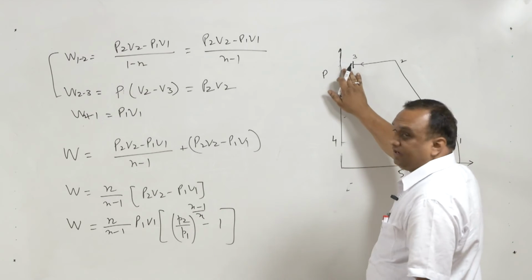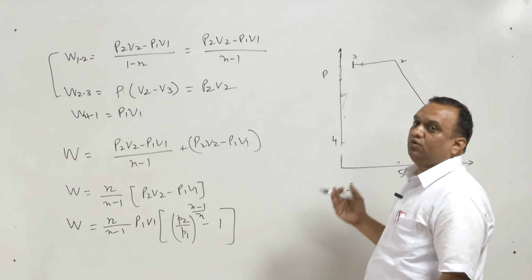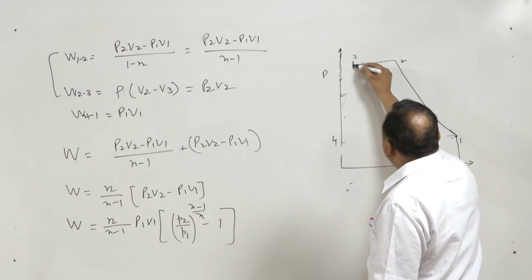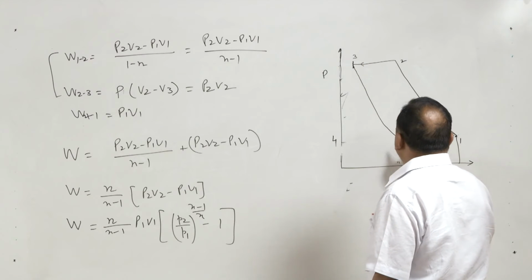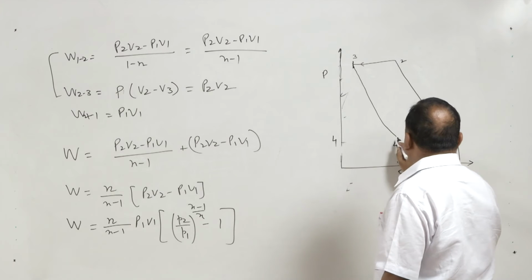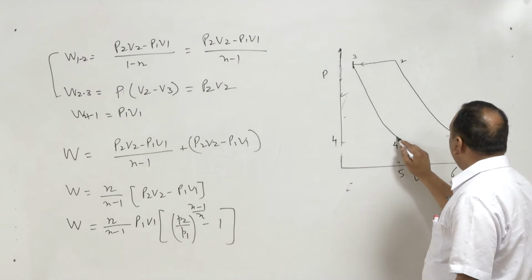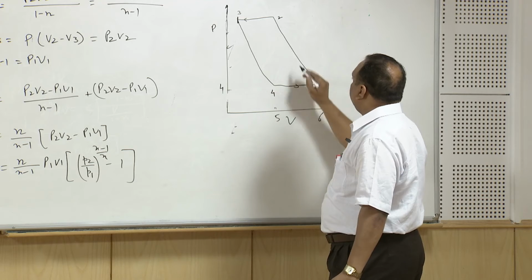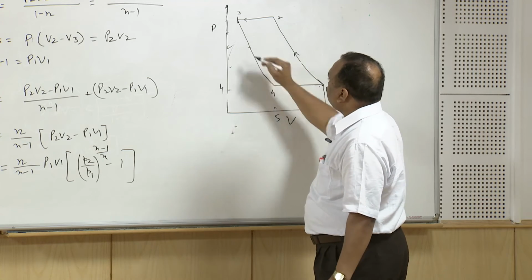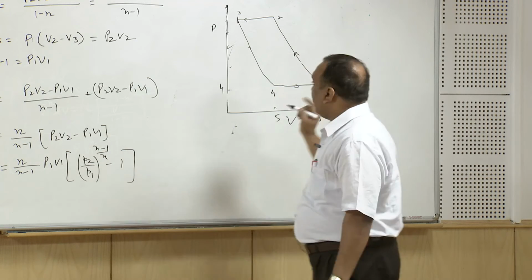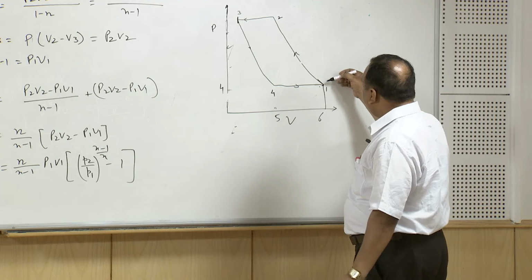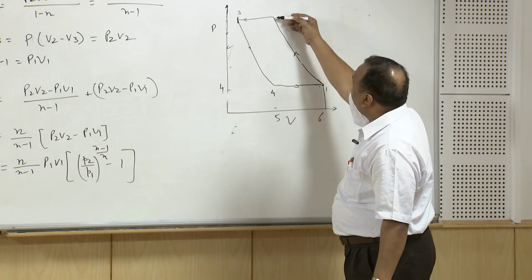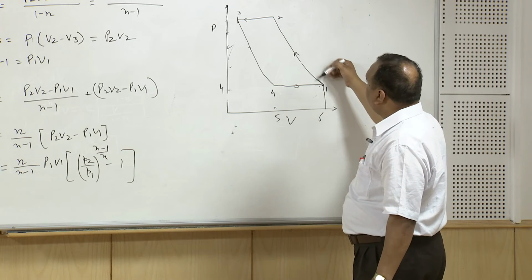Here we have compressed gas which could not go out of the compressor, so the expansion of this gas takes place, state 4 is attained, and after attaining state 4 the suction of vapor takes place. So, this is the actual cycle where initially the compression takes place at the bottom dead center.